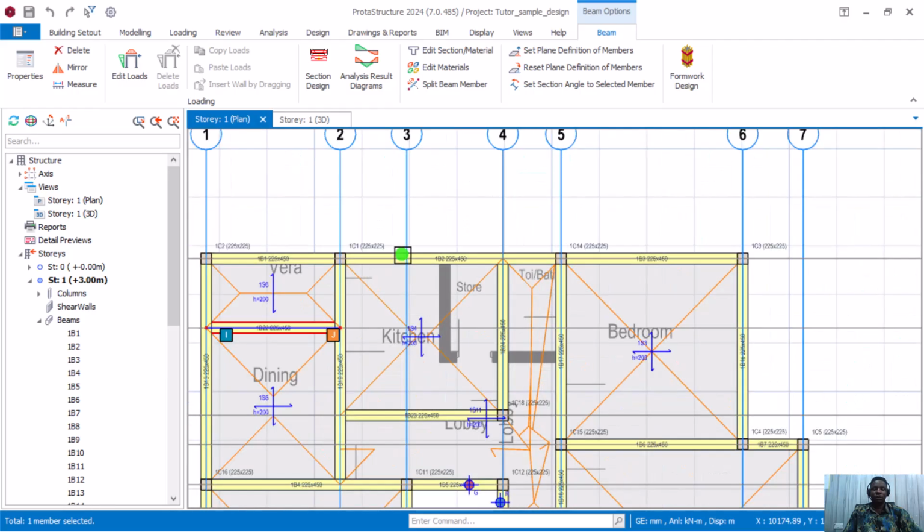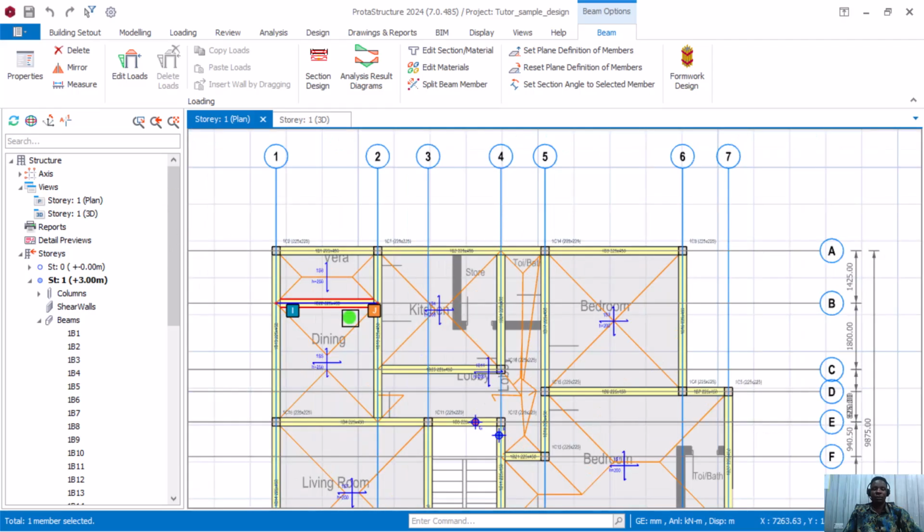But when we have a continuous beam in this nature, then what happens? We are going to hinge both ends. We're not going to hinge the internal supports. We're not going to consider either span separately. We're going to consider this beam to be a continuous span. We're going to hinge this I end, this J end, and we consider this to be the I end of that particular beam.